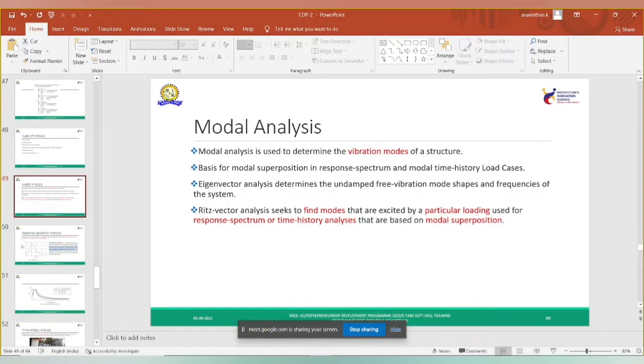Let us discuss response spectrum analysis. Before going to that, let us understand what modal analysis is. In dynamic analysis, a structure is considered as a model. In static analysis it is different, but here you will be considering all the masses as a mass M. It might be the mass due to slab dead weight, wall load or live load. All the masses are considered as a single weight in the floor. Whatever your hall dimension might be, it is taken as a single mass.